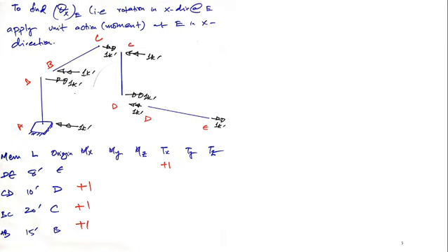Next, I have to find theta x in direction E. So for that I have to apply a unit moment in mx at point E. That's why I've applied a unit moment here. So this would be balanced here, equal and opposite. That joint D has to be balanced, so it has been balanced here. It is balanced here. Again, this joint C would be balanced.